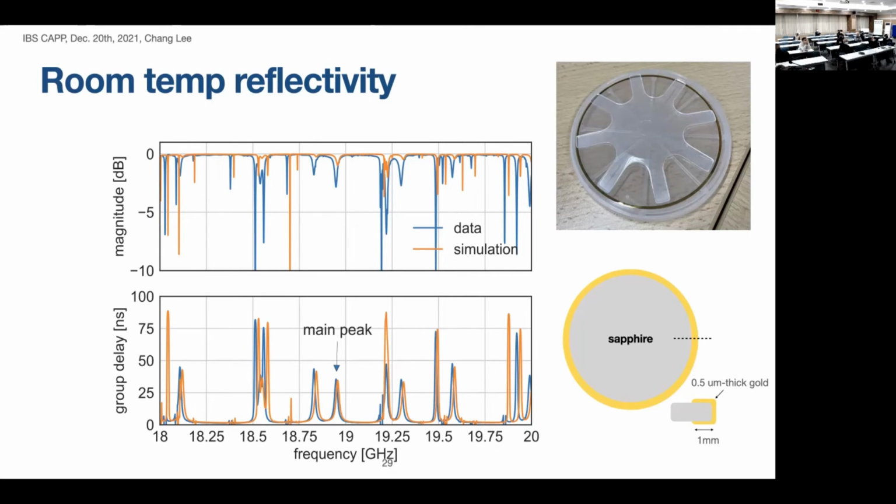So this is not bad. It doesn't critically lower our boost factor. Just a side note, initially we saw much larger loss. It can easily go below -10 dB, and then this turned out to be loss at the rim of the characteristics. And I solved it by applying gold layers on the rim of the substrate.